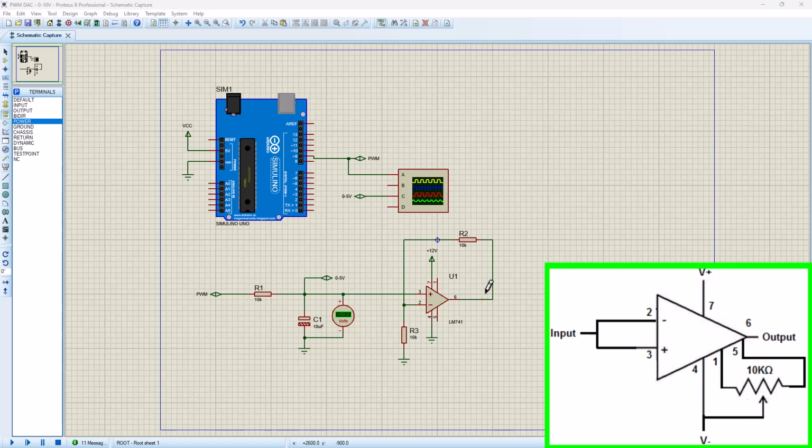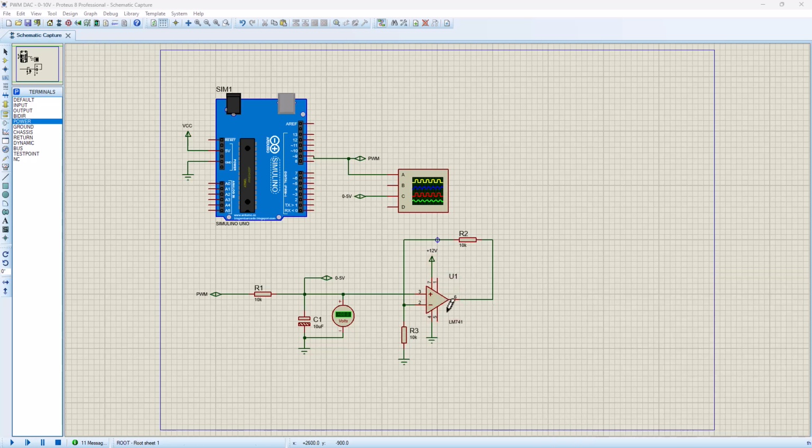Now, this is very important if you are amplifying very small signals. Right now, we are amplifying a signal that is up to 5 volts, so we're not too concerned about that. But if you are amplifying millivolt signals and you're working with real devices, you need to make use of these offset null pins, pin 5 and pin 1. Connect and adjust them so that your output will be 0 when there is no input voltage. Okay, so now enough said about the op-amp amplifier here.